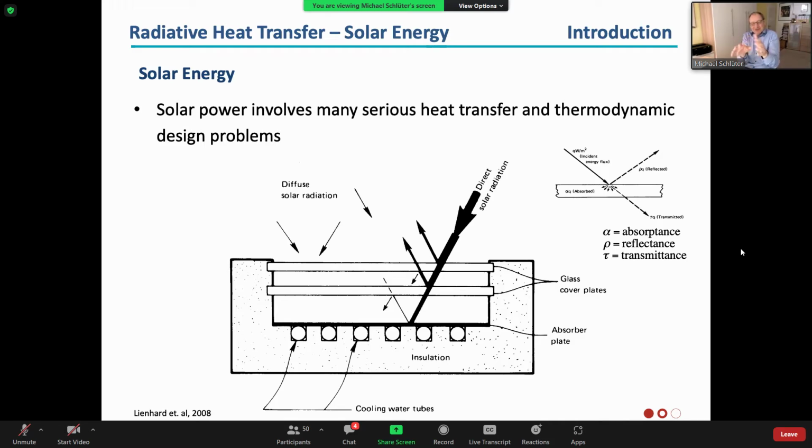And what you need to know is that it's a double walled system, and the inside is vacuumed. And this is to prevent convection inside. If there's no gas inside, then you have no convection, and then you have a very good isolation against heat loss.